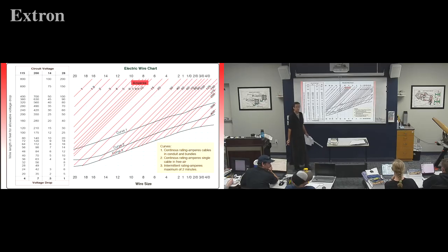So in that case, you have to run your wire at least 20 feet through it. So this one, they said you can run it shorter, it's fine. But you can't run it longer. So you can keep it at 10 feet.